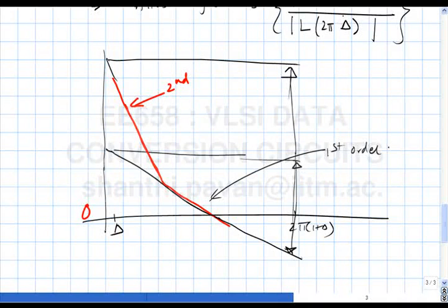And it also makes sense from an application point of view, because if you use a second order modulator to begin with, that basically means that the in-band quantization noise is much smaller than what you would have got for a first order modulator, which means that your alias rejection also should get better.